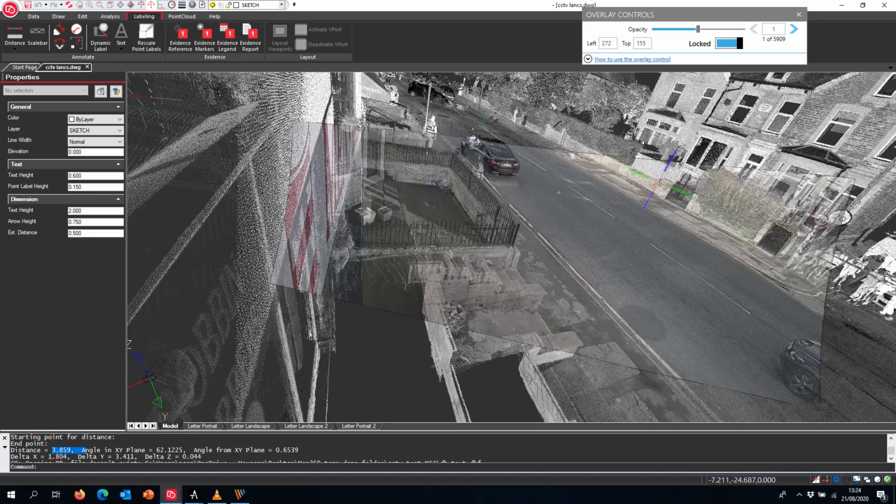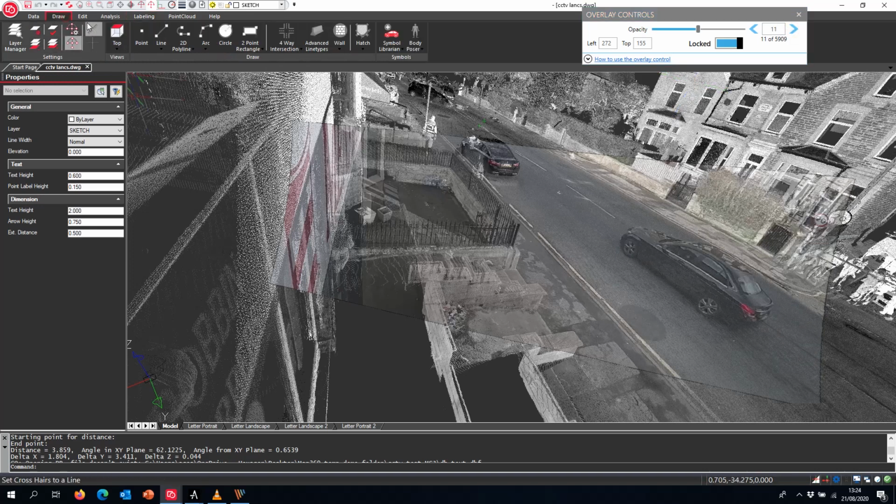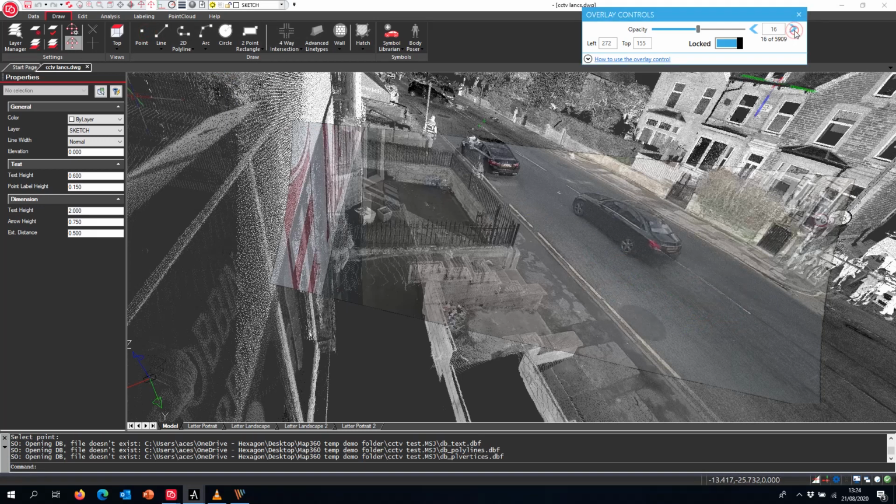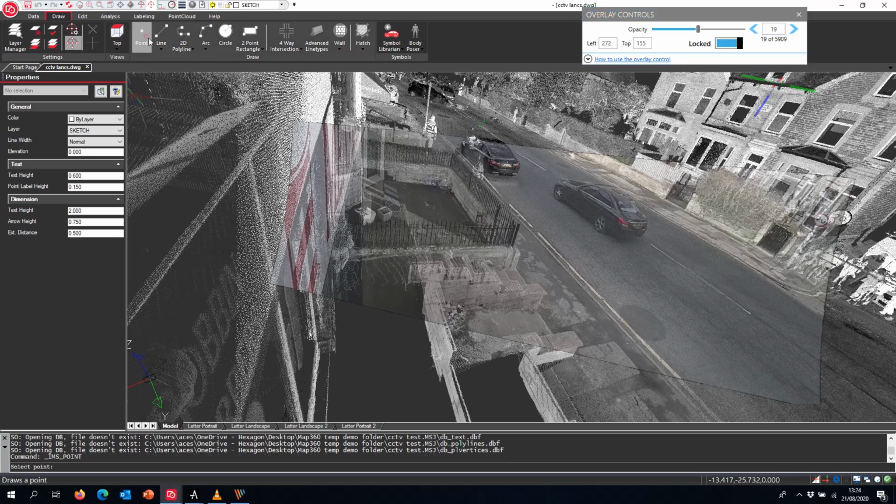Okay, like so. Which means then if I move my vehicles by each individual frame, I can then start creating points and lines to line up the front and the rear wheel track. So I can create a point position over there, and I can create another point position over here, and then I can move the vehicle a few frames up, and I'll do the same.